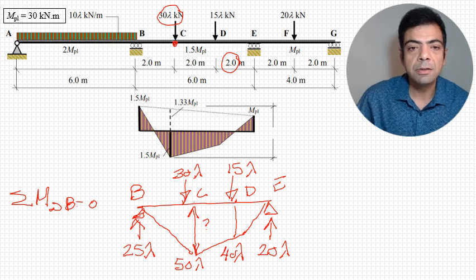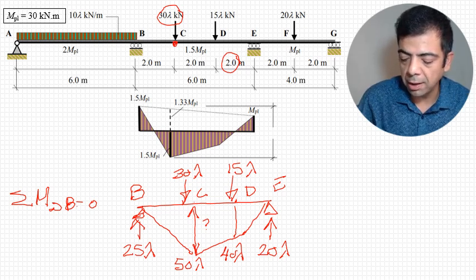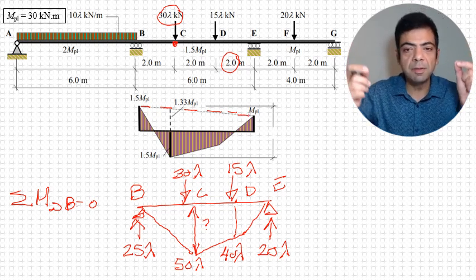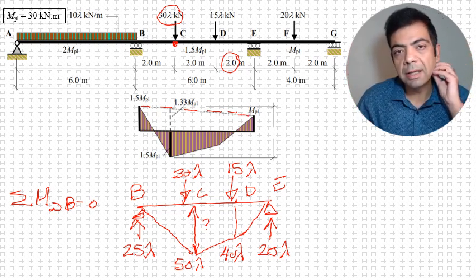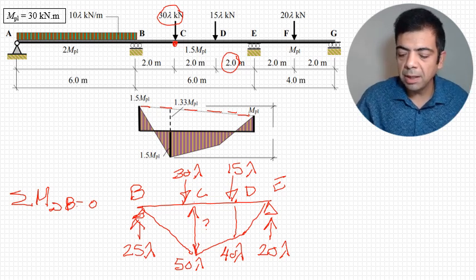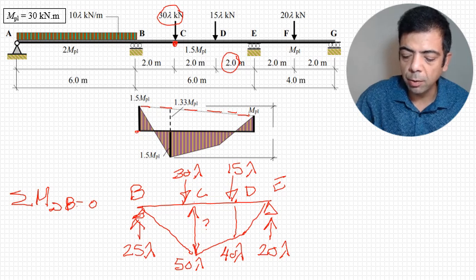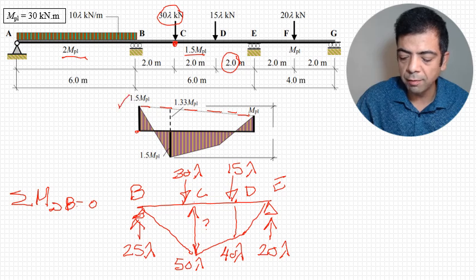All right, so we know that if we connect the dotted line and put the shape of the simple beam, we will get the bending moment at collapse. What is going to be the bending moment at collapse for point B? I'm going to take the smaller of these two values, so we take 1.5.